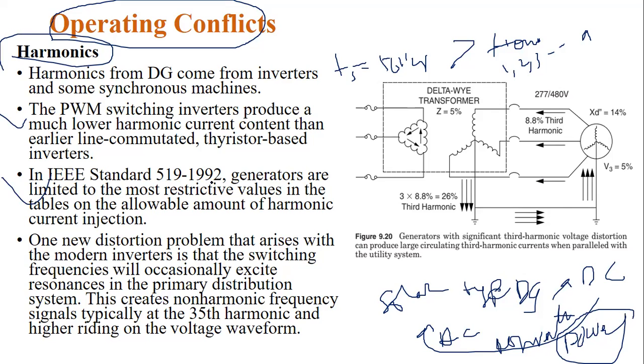So what are harmonics? What is the harmonic frequency? What is the normal frequency? How do we calculate harmonics? Then, based on the performance, the impact on the system and other things are given by the IEEE standard 519 from 1992. So how do we eliminate these harmonics from the DGs in the system? In this diagram they discuss the third order harmonics, the order of three.